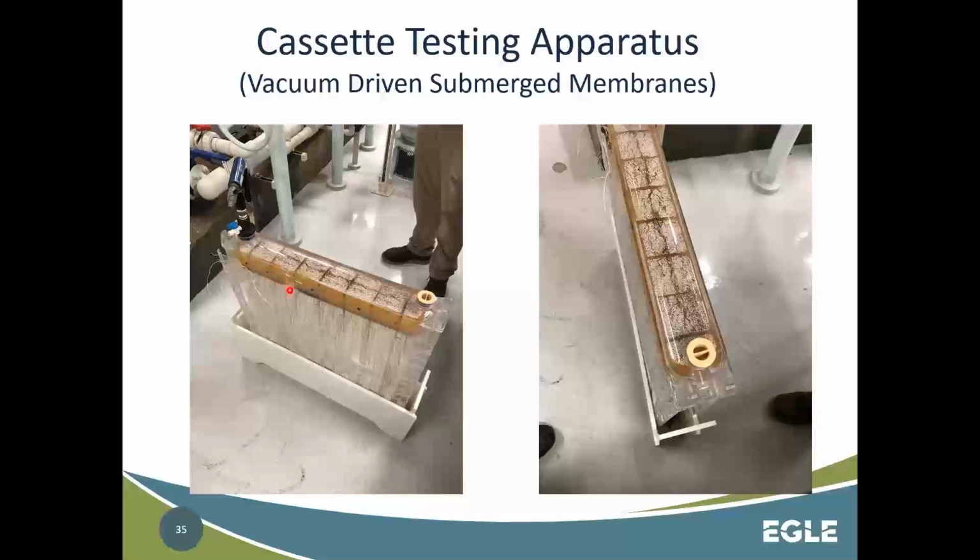So the membranes are in this plastic cassette, and here it's in the test chamber. I believe this is where you connect up your compressed air, and then you just watch, same thing, if you have bubbles coming up out of the potted end. I think with these, rather than pins, you just put some resin in there to seal it off.